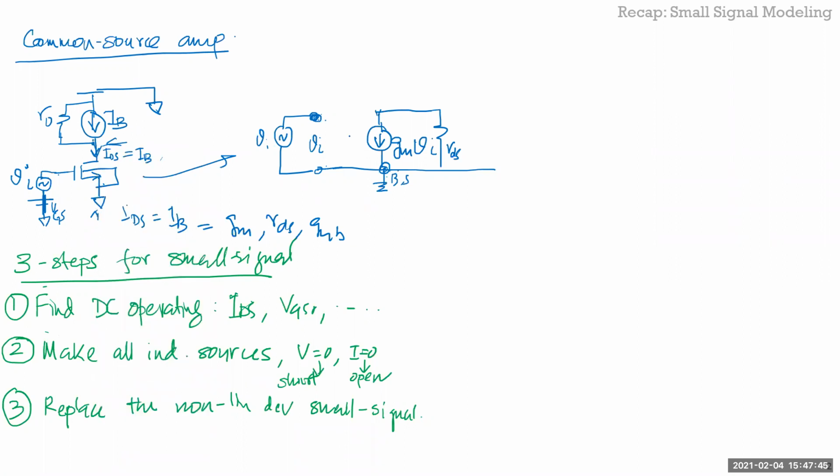So if the current source was the ideal current source, then that's it. That's your model, because your output impedance is infinite, because the current source is 0, right? So you basically open the DC part. Whatever impedance is left, that's the only thing which is across that current source. If it is ideal, there won't be any R naught. You don't have anything else. If it is not ideal, obviously nothing is ideal, so it has some output impedance. In this case, it's R naught.